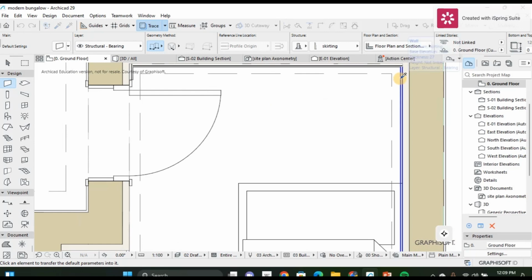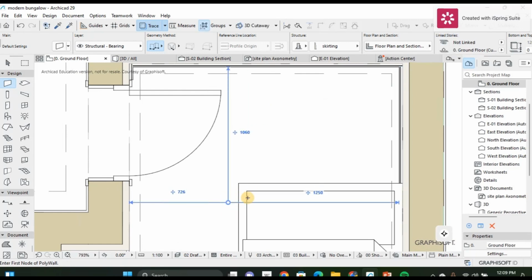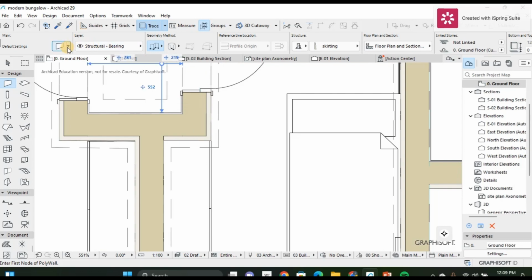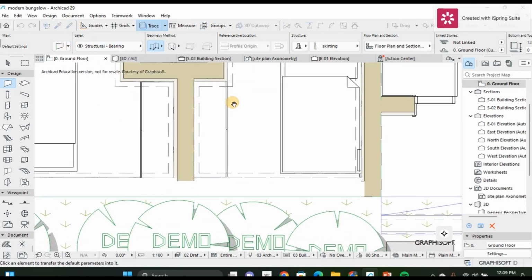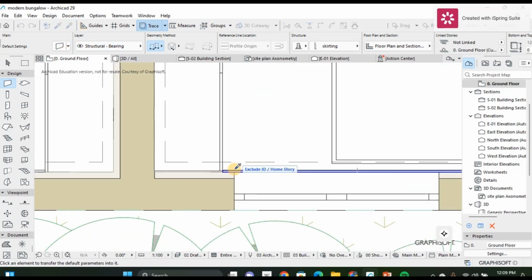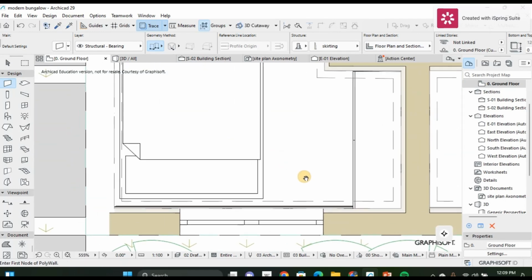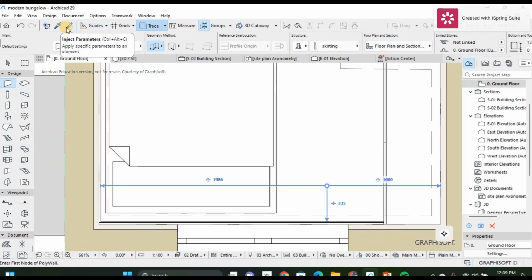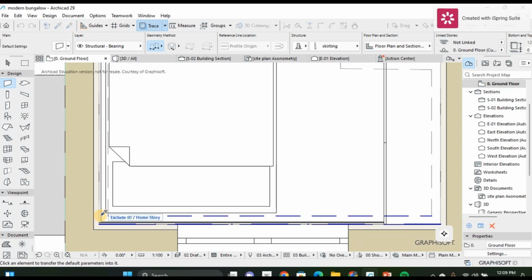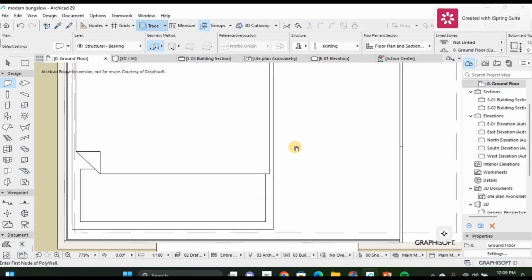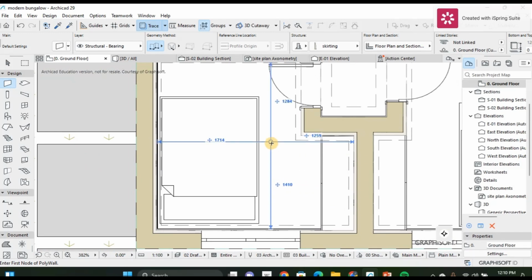So I'm going to do that for all of them. I'm going to come like that, take my syringe and inject in every one of them that's there. The only mistake I did is I did not fix the height first before I started drawing. So make sure you put your height first, the height above the ground for your skirt, before you start drawing your skirting.